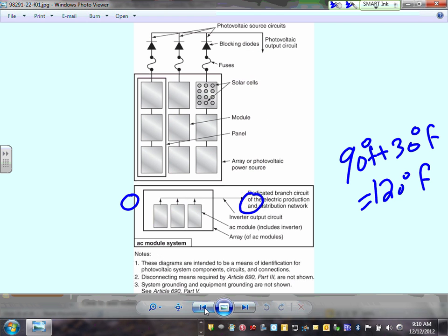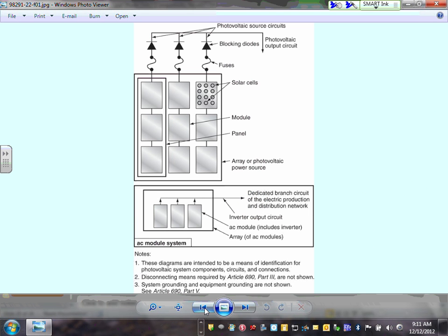And basically that's about it, gentlemen. Any comments, any questions about photovoltaic systems? It's a great skill to have. Really no rocket science. You have enough information in this chapter to get you started in designing as well as installing a system. The only difference from what we have done before is you multiply the DC by 1.25 twice when you size the cables. And you use the open circuit voltage and adjust the voltage because of the temperature. That's really the only thing, and a lot of disconnects everywhere, and labels.